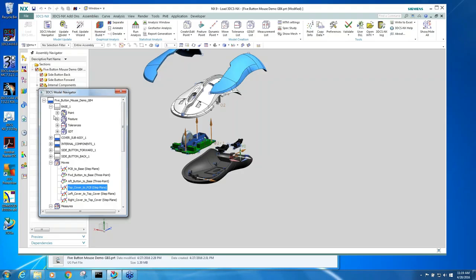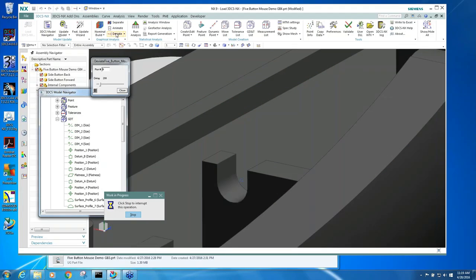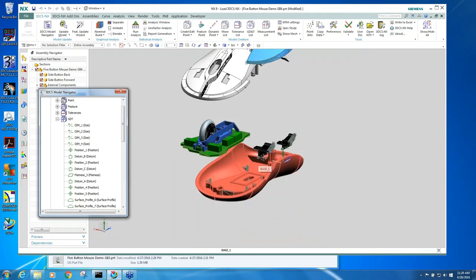And then at the part level, if I go into the base, the part level is where we actually have the tolerances. You can see that happens to be one of the features that locates the side mouse button. It's got a location tolerance on it. Now when this number is changing because the model is not built, you're seeing component part variation. Every time this number changes, it's like we grabbed another component out of the box, it was molded, and this hole is within its defined positional tolerance. That happens to be the locator for the button.